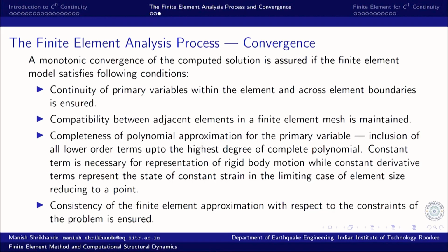And then finally, the finite element approximation should be consistent with the constraints of the problem. For example, if there are two different fields of displacements or deformation, and there is required to be some relationship between these two fields, then the approximation that we use should not contradict those relationships, the basic physics of the problem.